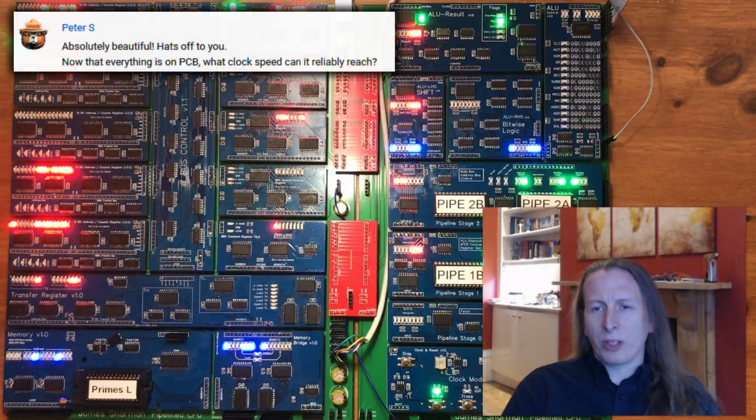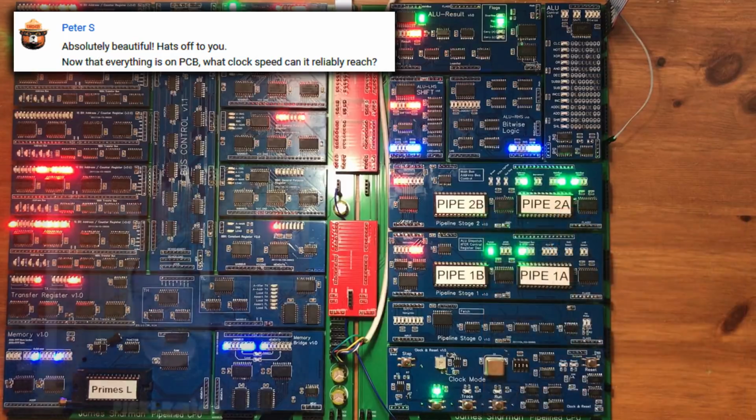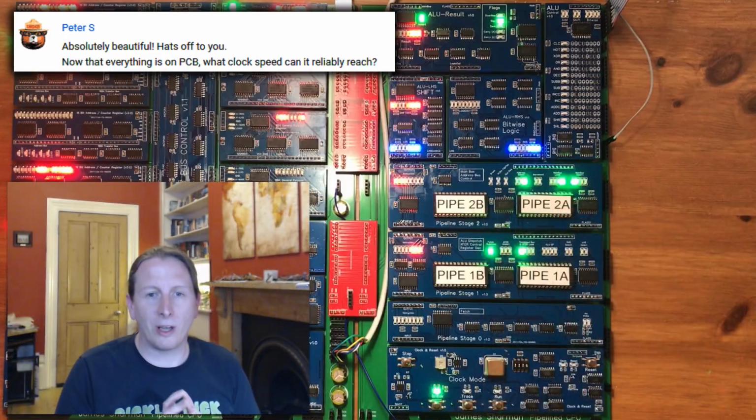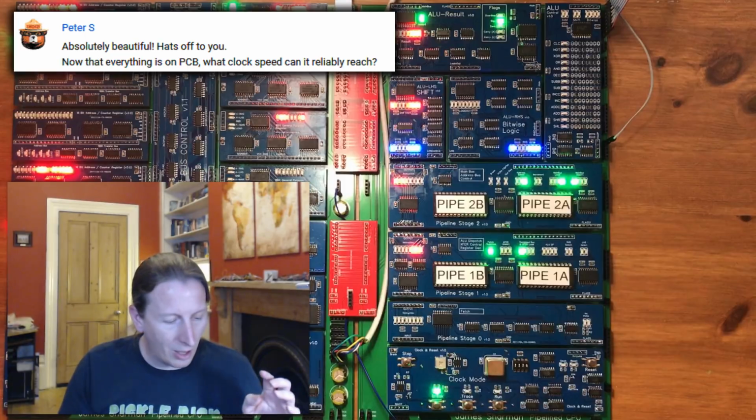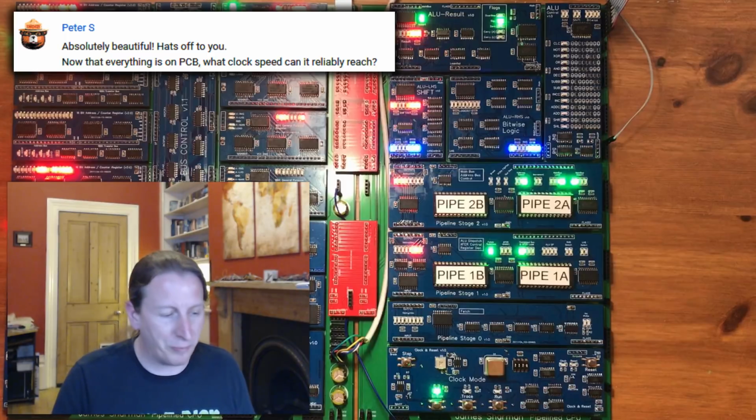Peter is wondering what clock speed it can reliably run at now it's entirely on PCB. Oh, that's a good question. I don't know. At the moment, I've got a 2 megahertz crystal in there, divided by 2, so it's a 1 megahertz clock rate. This was predominantly just something I stuck with. I've got a 5 megahertz crystal that I was running divided by 2 for 2.5 megahertz, which was the highest I've demonstrated it running at.